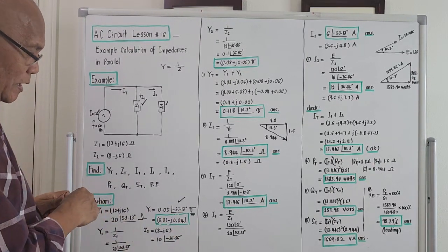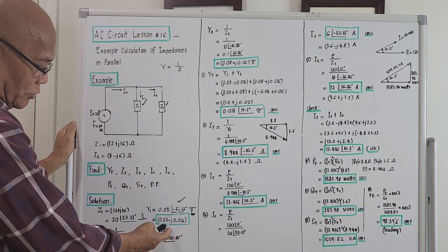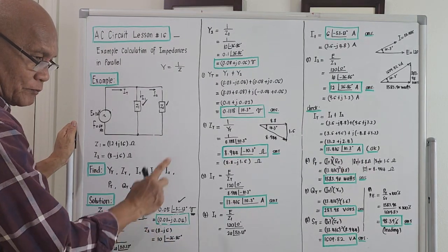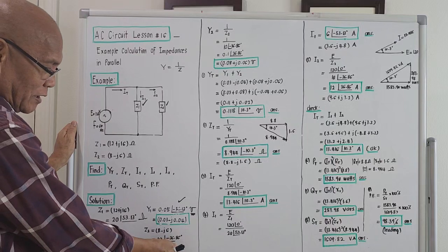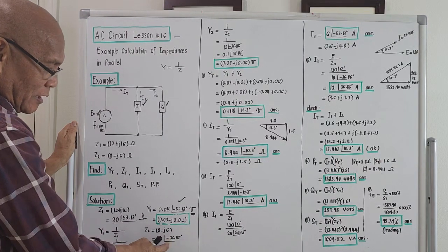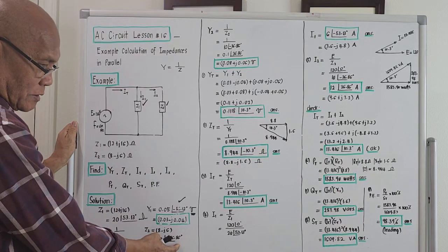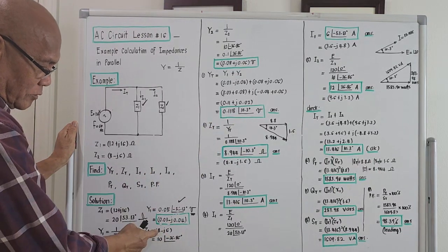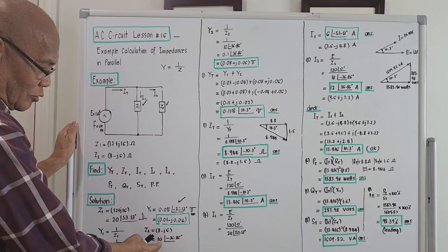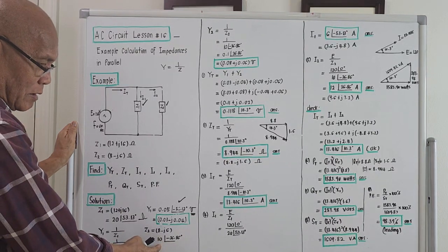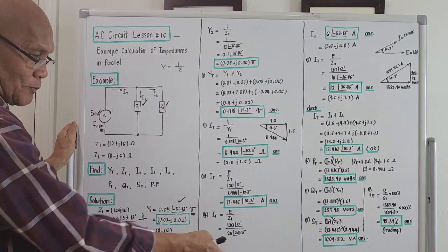Converting to polar, you take the ratio 6 over 8. Press arctangent, what will come out is negative 36.86 degrees. Negative, because this is minus j. Take the cosine of this, you divide that to the value 8, what will come out for the magnitude of C2 will be 10. So we now know C2 in terms of polar.